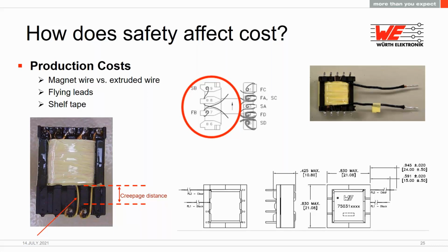Likewise, the magnet wire can often be directly soldered as well. The high-temp lead-free solder quickly eliminates the enamel coating and creates a quality solder joint on the bobbin terminal. The extruded insulation is different in the fact that it generally cannot be directly soldered without first stripping the insulation off the wire and then manually terminating the winding. There are some solderable extruded insulated wires on the market, but it's easy for these extruded insulated wires to be thinned or cracked or deformed when they're exposed to the high temp solder.